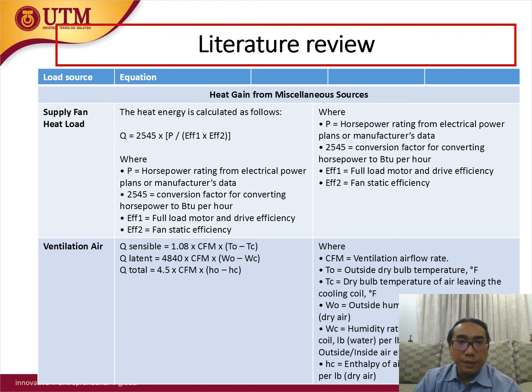Instantaneous temperature rise in the air stream due to fan drive inefficiency. Temperature rise in the air stream when the air is brought to static equilibrium and the static and kinetic energy is transformed into heat energy. The location of the fan and motor relative to the cooling coil and space being conditioned determines how the heat is added to the system. If the fan is downstream of the cooling coil, draw through, then the fan heat load is added to the space cooling load. If the fan is upstream of the cooling coil, then the fan heat load is added to the system cooling coil load.